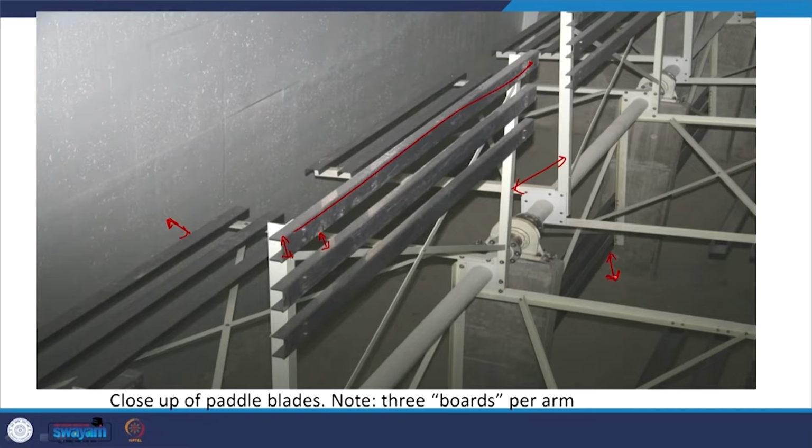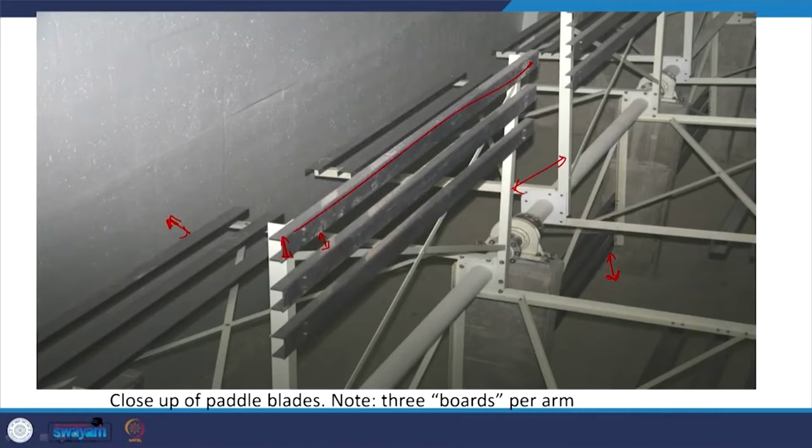These general spacings are relatively easy to do. You have thumb rules and relevant tables to guide you. But for the width and length, and how many paddles, let's say 1, 2, 3 or such, you will have to look at the level of mixing that you want, and based on that you will come up with the relevant paddle boards, right?